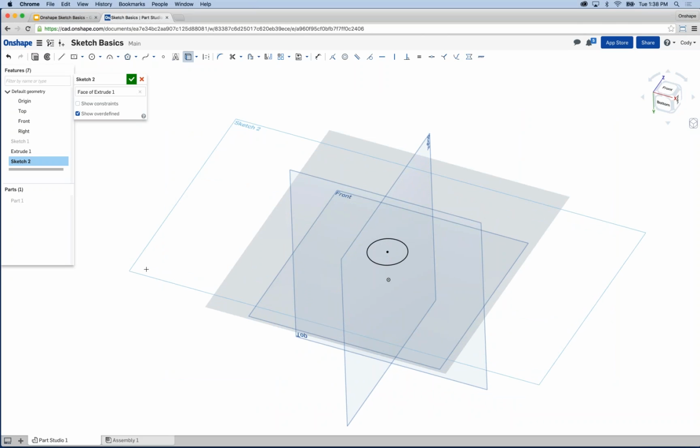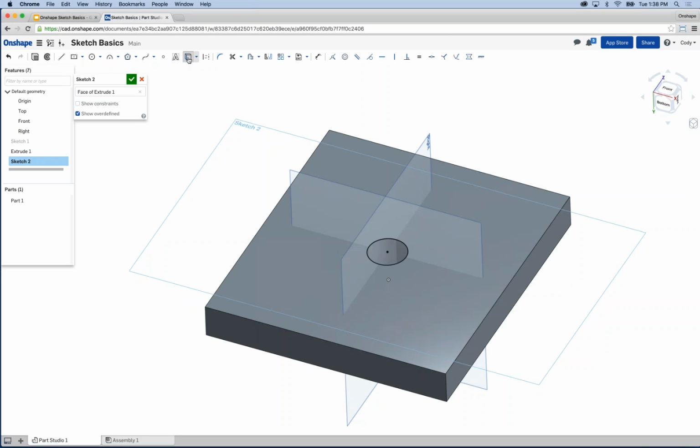The neat thing about this is if I change the original circle, this sketch will automatically update. So I'm building a bit of design intent into my model, and I'm making it so that when I make a change, I don't create this domino effect of errors that I have to rebuild because I've correctly reflected my intent. So just a tip, the use command is very valuable for converting faces or edges or even other sketches to the current sketch. And it allows you to reuse geometry in an efficient manner that allows you to reflect the intent. So let's move on.